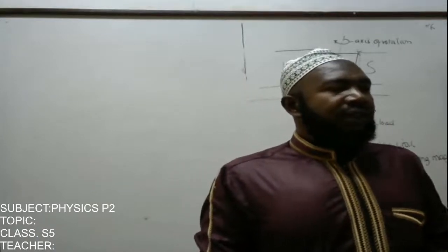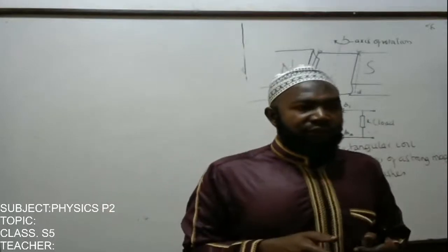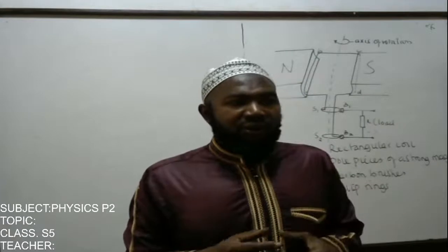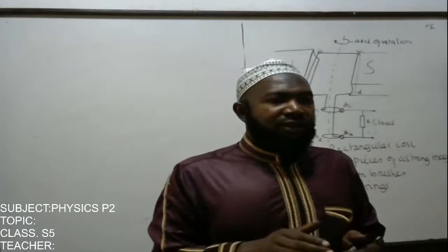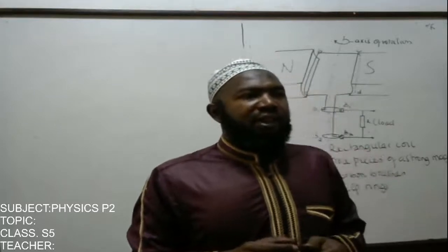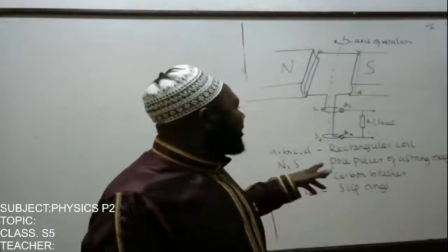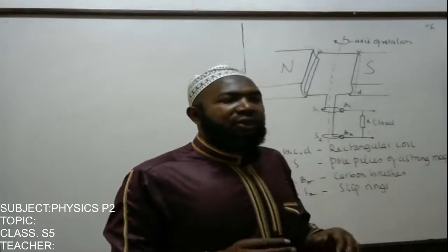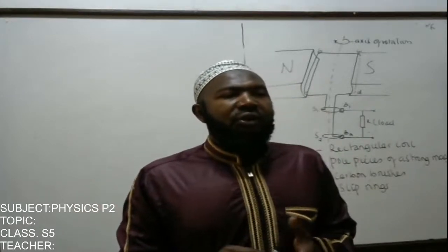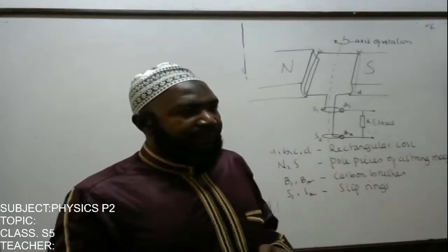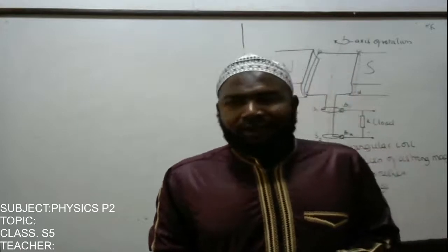Now we are saying when the coil is in the vertical position, as will be illustrated in the video, EMF is 0. As AB begins to move downwards and CD upwards, EMF reverses in the coil. Since the rings S1 and S2 maintain contact with the same carbon brushes B1 and B2 respectively, current also reverses in the load R. Hence the current supplied to the load R is an alternating type of current.